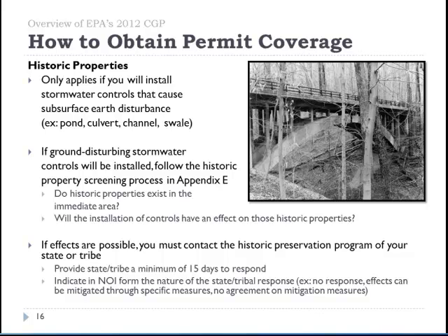Alternatively, if there were and potential effects could exist, you would need to contact the state or tribal historic preservation program and provide them a minimum of 15 days to take a look at the information you've provided them, and we've spelled that out in Appendix E. And then indicate after those 15 days what the nature of their response was, whether they got back to you and indicated no problem, whether they provided recommendations on mitigation measures, or whether they didn't respond.